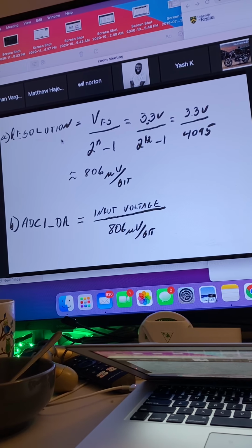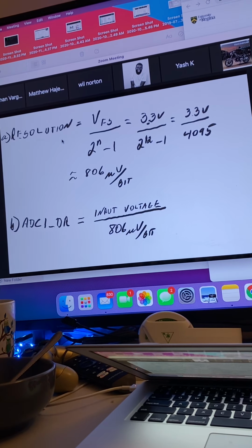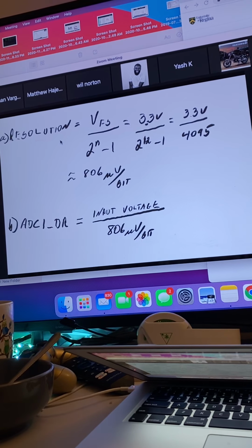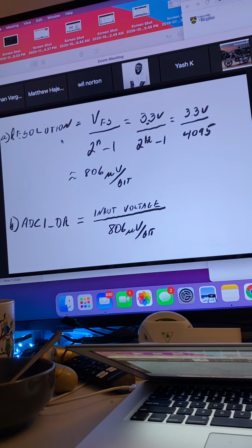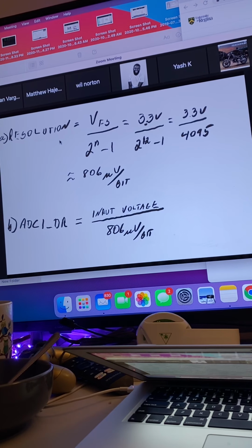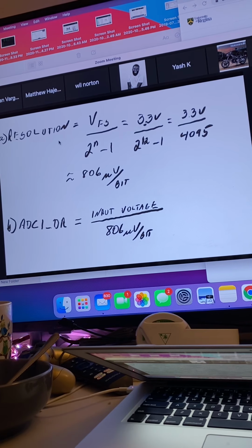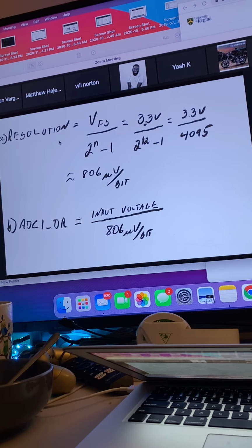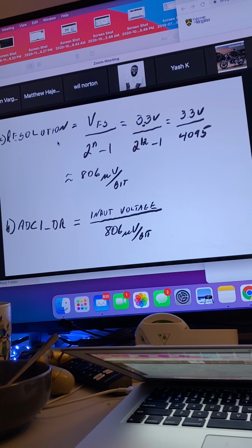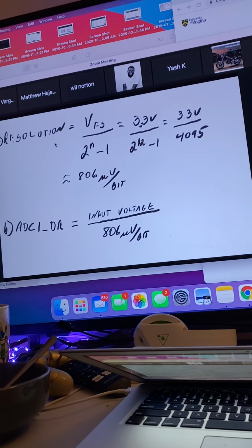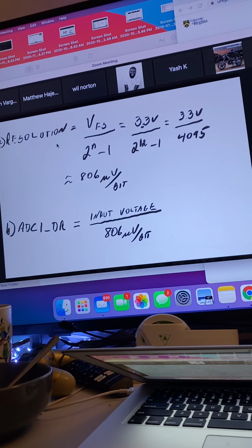FFF would be equivalent to 3.3 volts. Now there's a little bit of error in there, because there's a half step that's applied at the beginning of our conversion range. We're not going to worry about that. If we see FFF, it's close enough to 3.3. If we see 7FF, that's halfway, roughly 1.65 volts. If we were to see 3FF, that's a quarter of the way, about 0.82 volts.